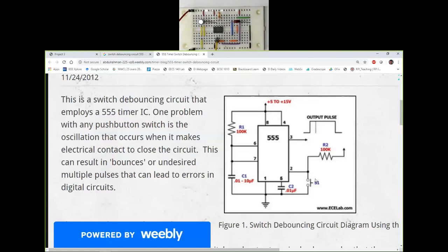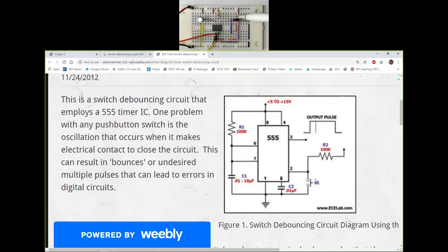Perhaps this is going to be my input, so I like channel 1 to be input. I'll put my orange wire, which is my scope channel, on pin 3. Pin 4 should be connected to VCC, the supply voltage. So pin number 4 goes to this purple wire here, jumps to that point, using another purple wire jumps to that point, and then a red wire connects it to high. So that's how pin 4 is connected to high there.